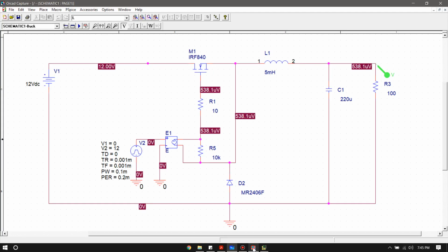So in this circuit setup, if we have only the pulse generator going to the MOSFET, we don't have any opportunity to connect the source terminal to the ground, because we want the bias voltage to appear across the gate and the source. This is the gate terminal and this is the source terminal. If we use a voltage controlled voltage source here, we can generate another ground.